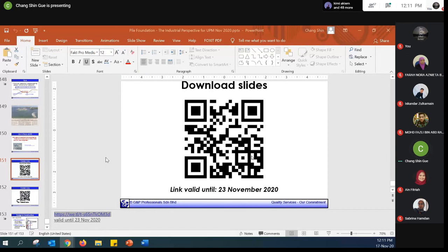In general, what is the spacing? What is the distance between the pile and the outer layer of the tunnel? In practice, we would say something like one or two times the diameter of the tunnel itself, but that is just to start off. You have to carry out the analysis to make sure of the induced stresses from the tunneling and how it responds to the building, and vice versa, how the loads from the building transfer to the tunnel.